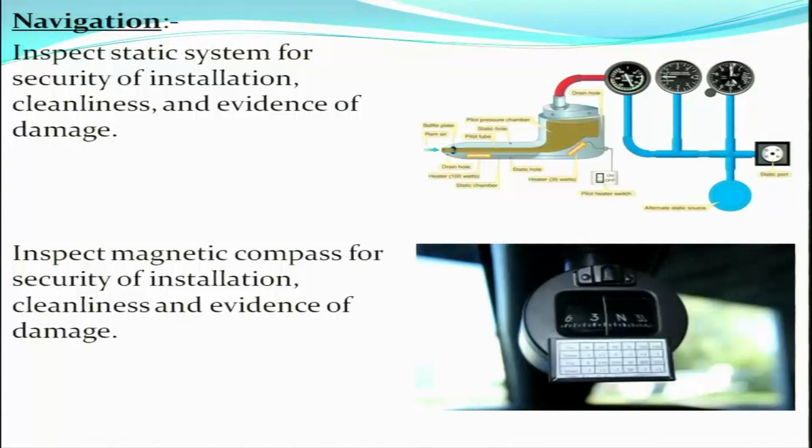Now coming to navigation, inspect static system for security of installation, cleanliness and evidence of damage. So the complete pitot and static system, this is the pitot tube. The pitot tube is inspected, all the lines are inspected, all the drain points are inspected, the static ports are inspected for cleanliness, evidence of damage, for security of installation.